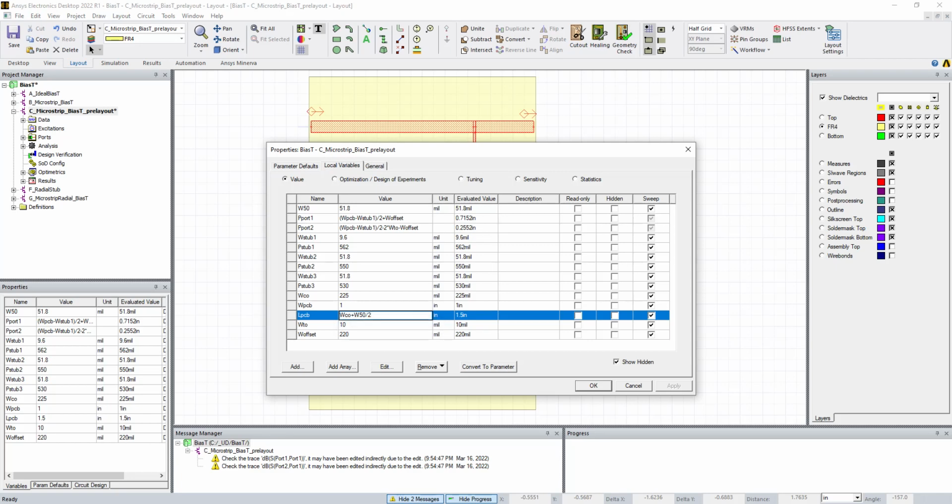That brings us to stub 1, plus P of stub 1, plus W of stub 2, which is the width of that stub, plus P of stub 3, plus a trace offset, because remember, the dielectric sticks out a little bit more.